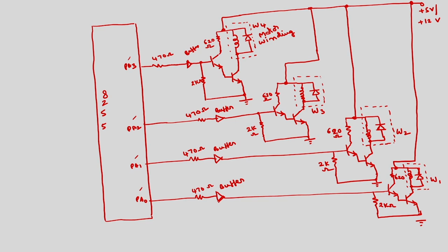I want to operate this motor at a speed of... these are the specifications. You have to first decide the specifications before writing the program. The interfacing is the same. How much delay is required between two consecutive sequences? As I have discussed, the sequences that you have to give are 0 0 1 1, then 1 0 0 1, 1 1 0 0, 0 1 1 0, 0 0 1 1.